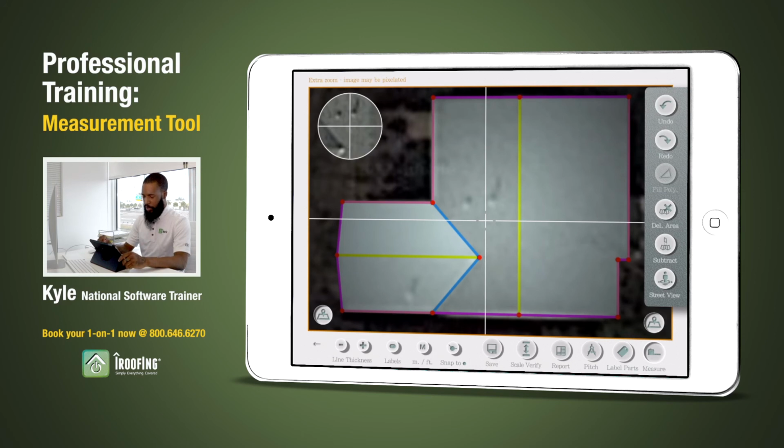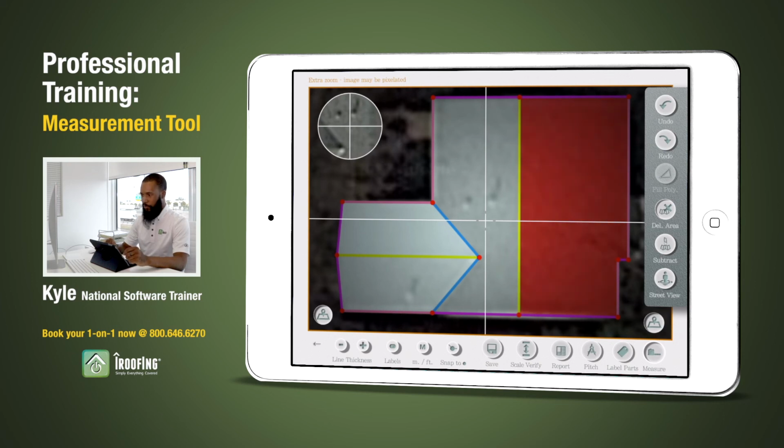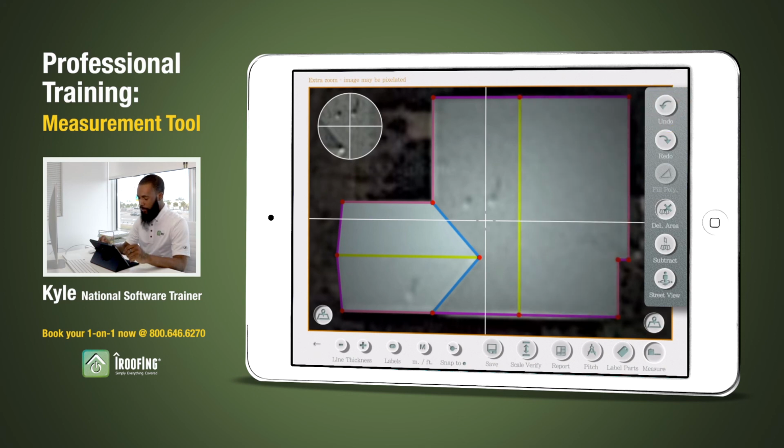Also, if you tap on delete area over to the right, I can double tap any slope that I have on the roof to remove it. So after tapping delete area, if I tap on an area, it'll start flashing red. Tap on it again, it will remove it. And if I ever delete anything by accident, I can hit the undo button up in the top right corner to bring back that area. And don't forget, when you're done, to turn off delete area by hitting the button again.